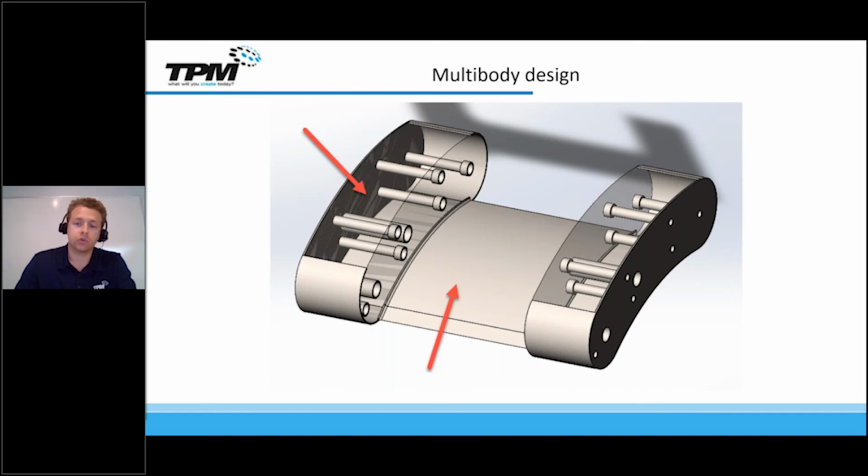In order to use our SOLIDWORKS model in nTopology, we first have to create a shelled body that is close to what the topology study yielded from the beginning. Once we do this, we can then export the CAD file and then import it into nTopology.